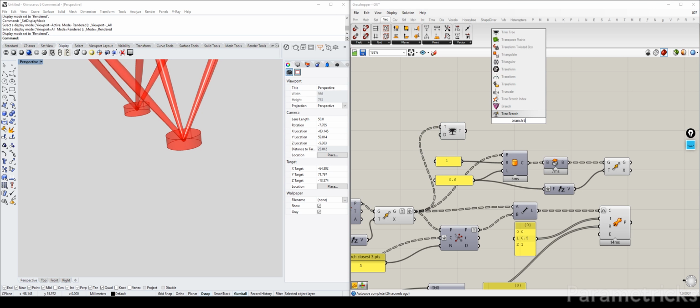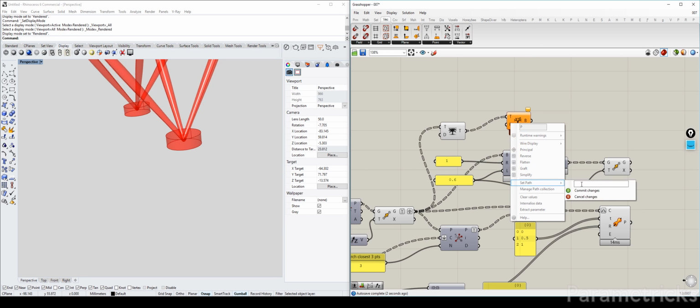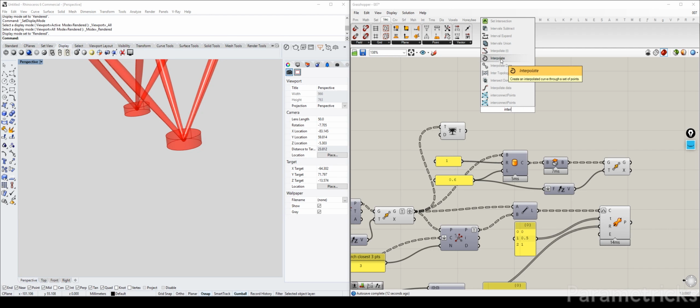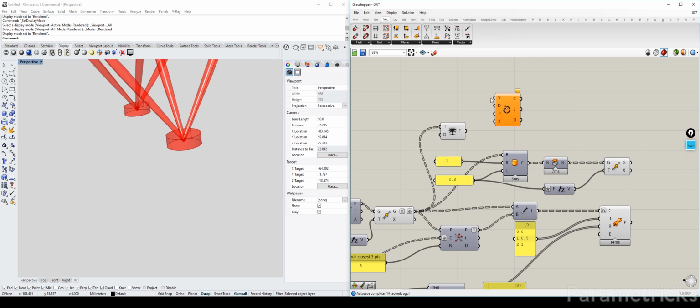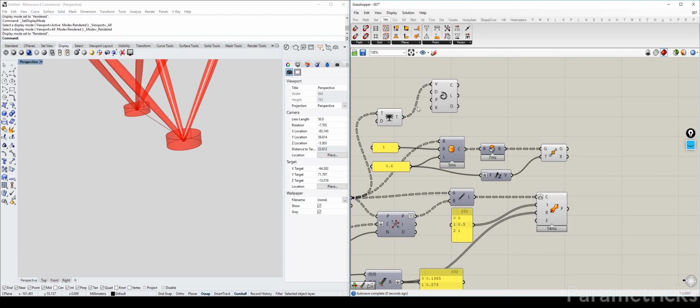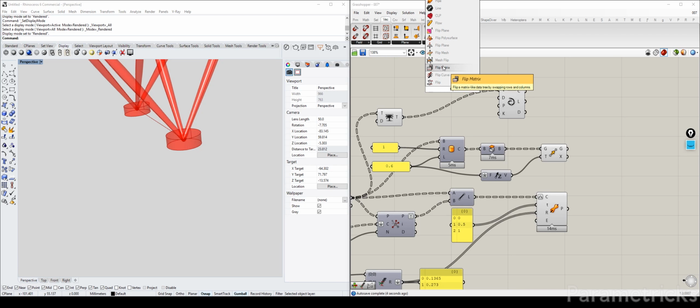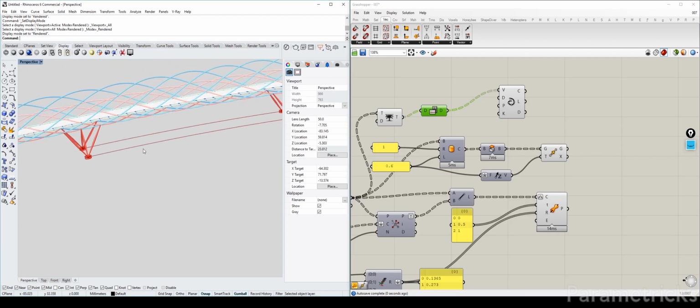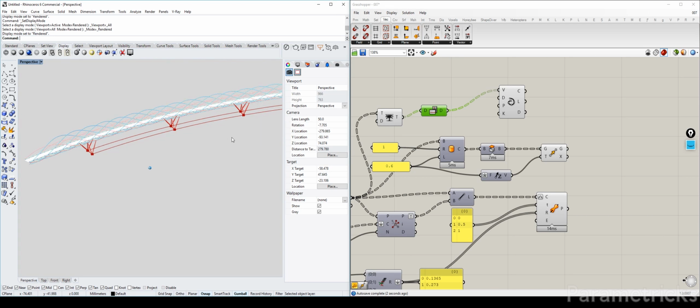And I'm just gonna confirm it, use the tree branch and set that to path 0, and I expect to select these 2 points, which I am, so that's good. What I want to do with this is create an interpolated line in order to get the vectors to move these points, and I believe this is the wrong interpolate, so I need to flip the matrix in order to make the lines that I actually want. So those are the lines that I need.